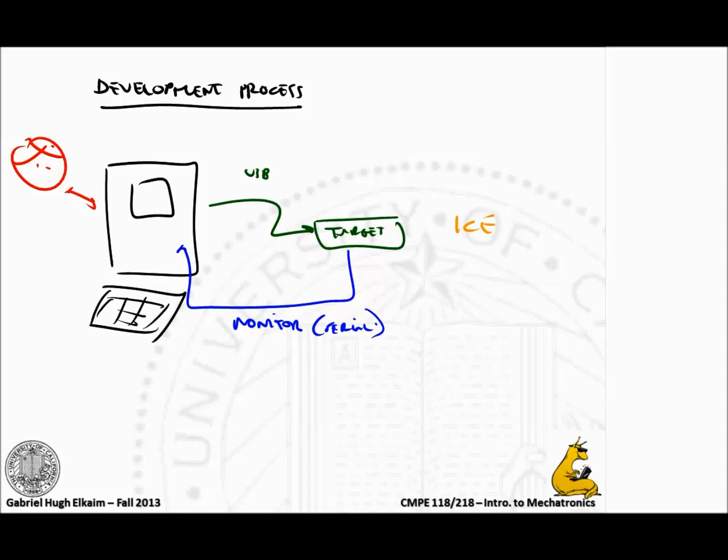In this case, on the Microchip ones, they take over 2 pins, and if you actually put the programmer on, you can halt the processor, look at any register, look at memory, do anything like that. In general, we won't be using those in this class, simply because you have the ability to flash the bootloader that we put on there for you. And if you have some really obscure thing going on, we'll bring it out and figure it out. But usually we don't need it. But those are available.